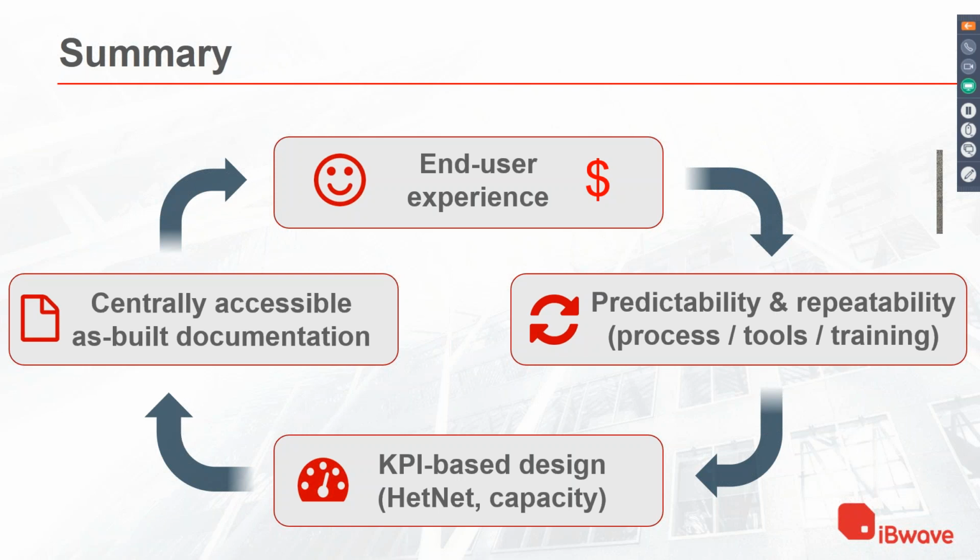We use a different algorithm on the tablets, and with fast ray tracing, you model everything and you get a bit more accuracy. You can do 3D modeling. You can do inclined surfaces for complex venues like stadiums. So at the high level you have the same functionality, but with more resolution and more precision with the tool. But they speak the same language, and you can exchange files from one to the other. So you can start with one, as we've seen in this particular case study. You start with mobile, do most of the work, and do the final touches on the PC, and then do the final reports. So I think those are some of the differences.